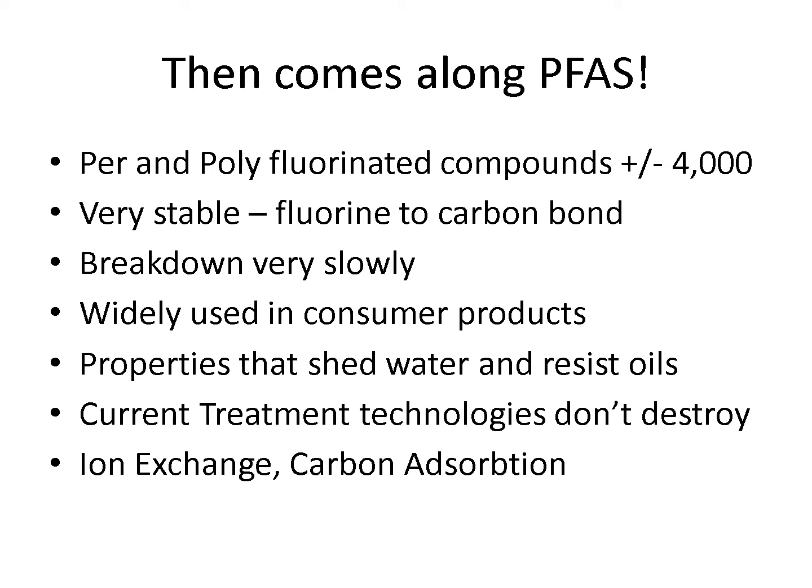Current treatment technologies for PFAS, importantly, do not destroy the compounds. They just concentrate those compounds onto another medium, such as ion exchange or carbon adsorption. You still then have those PFAS compounds that need to go somewhere, typically to landfill.